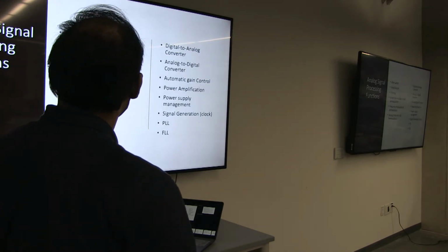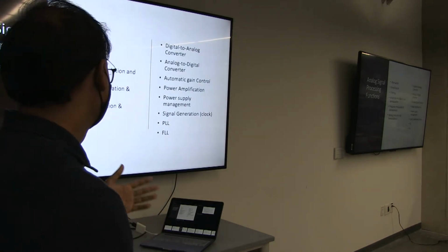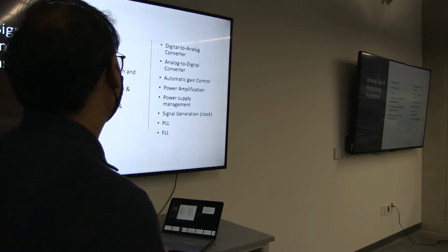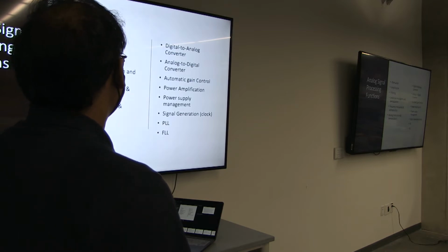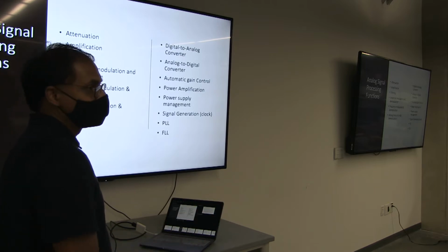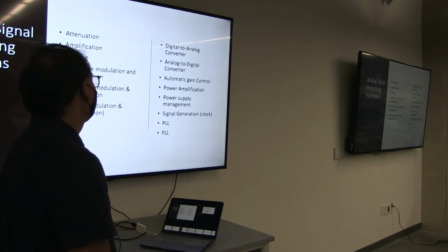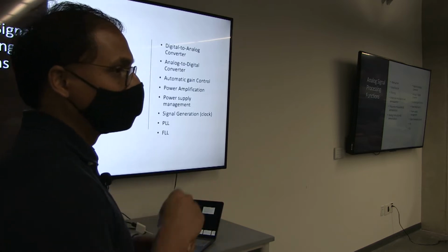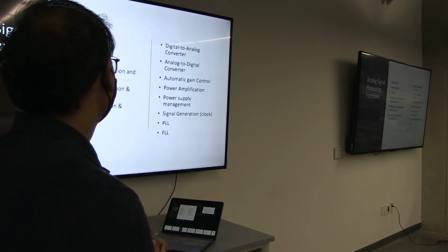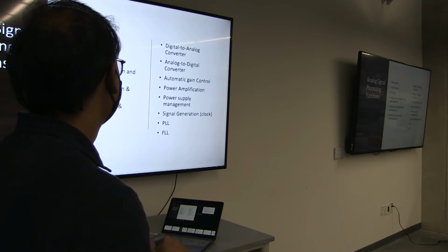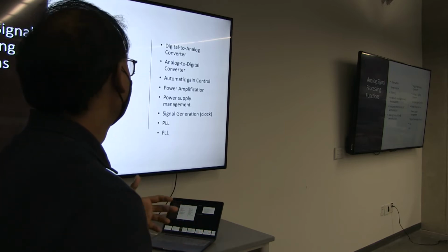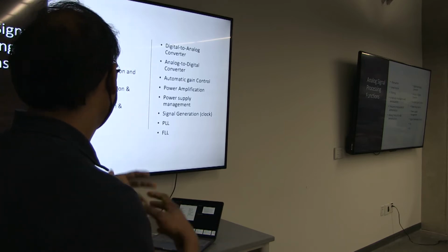So if you look at analog signal processing in today's chips, these are the primary functions that are done by any analog design engineer. Attenuation: any resistor network is an attenuator, and you can also use active devices to fine tune the gain or set a signal at a certain level to not oscillate. Amplification is again a standard function used for power gain, voltage gain or current gain. All those come under amplification, and today we'll be discussing filtering.